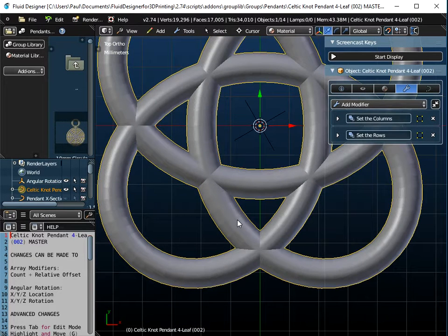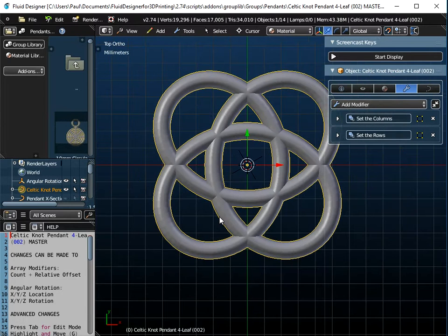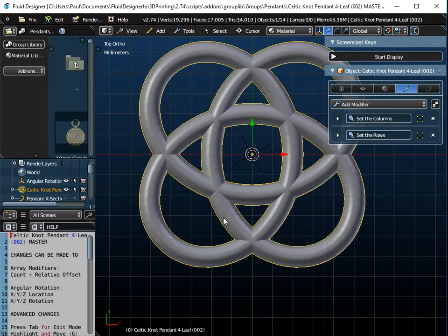This is actually a Bezier curve, this object, and in the previous video, we talked about converting these to NURBS curves instead of Bezier curves. If you do that, you will really escalate the file size here and the mesh size. I did it earlier, and I ended up with a mesh size of 2 million meshes and a 100 megabyte file, which is much too big.